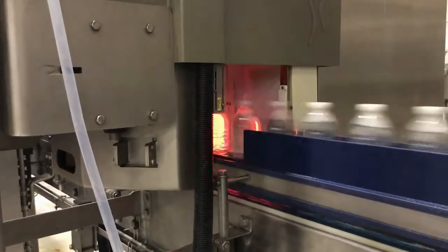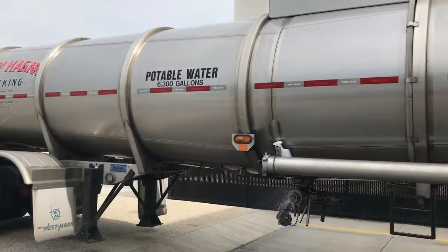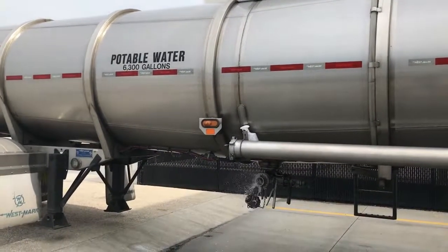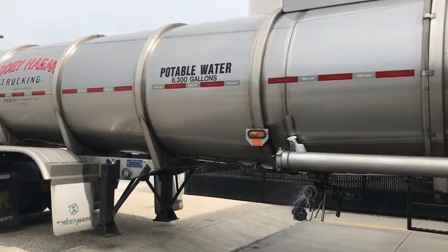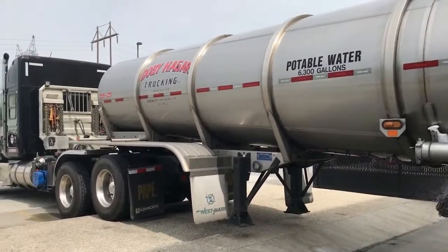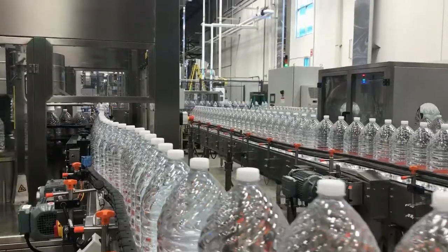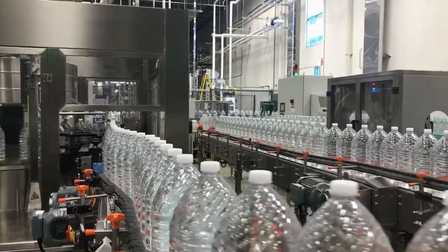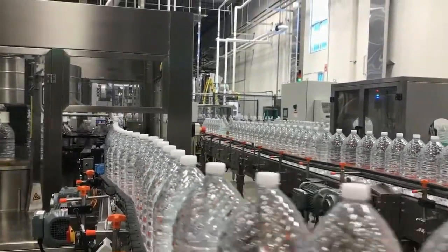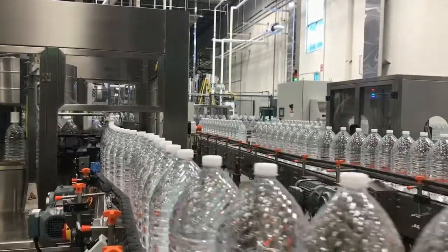The last CQP is spring water receiving. When we receive a spring water truck delivery, we must test TDS, bacteria, coliform, pH, turbidity, and chlorine levels. The FDA has a product of identity standard that applies to both purified and spring water. If you notice a quality problem or a test outside of critical limits, notify your supervisor or QA immediately. They will then determine what to do with the product and what corrective actions need to be taken.